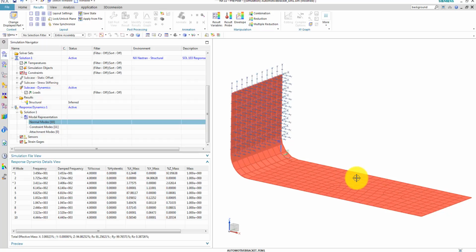Now, when we run the various transient and harmonic loads, we know that we can predict the response for each time or frequency step efficiently by calculating only 2 modal amplitudes. That's a great achievement without losing much accuracy.